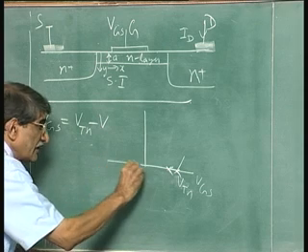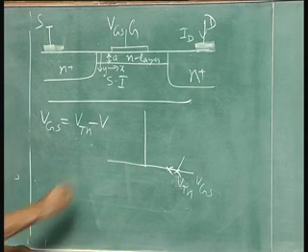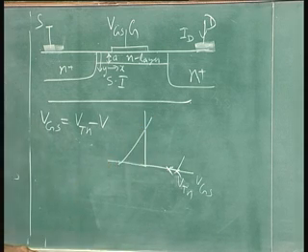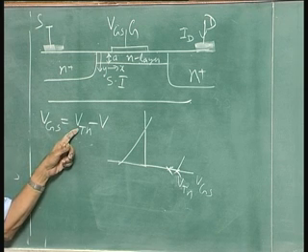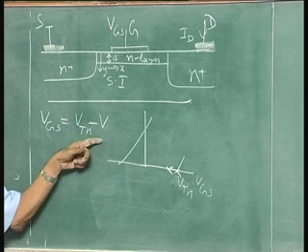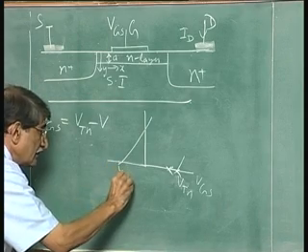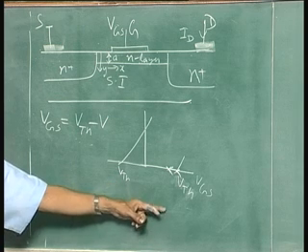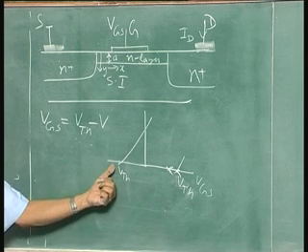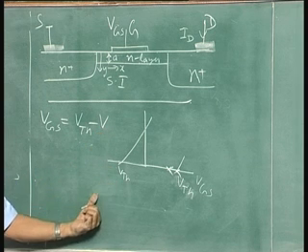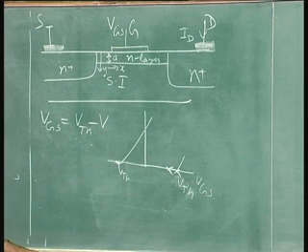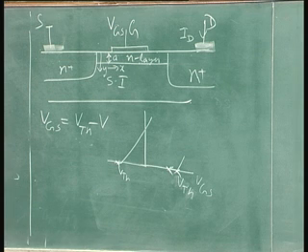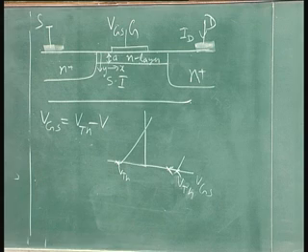In the depletion mode type of device, how does it work out? VTN is negative, minus 1 volt, let us say. If this is minus 1 threshold voltage, I have been using sometimes VTN, VTH actually. If this is minus 1, minus 0.5 volts, minus 1.5 volts, you are going down here. So, please understand the same formula, same discussion holds good for both enhancement type and depletion type. Let us plot the depletion layer for one particular case, because the whole same thing holds good.